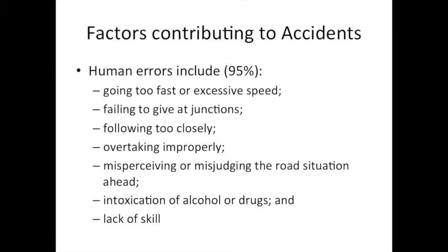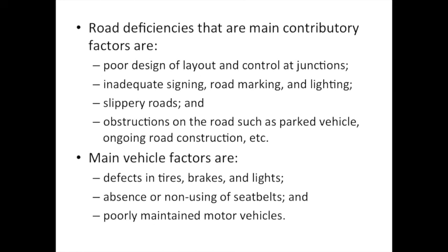Factors contributing to accidents. Top on the list is human errors, which is going too fast or excessive speed, failing to give way at junctions, following too closely, overtaking improperly, misperceiving or misjudging the road situation ahead, intoxication by alcohol or drugs, and lack of skills. Road deficiencies that are main contributory factors are poor design of layout and control at junctions,